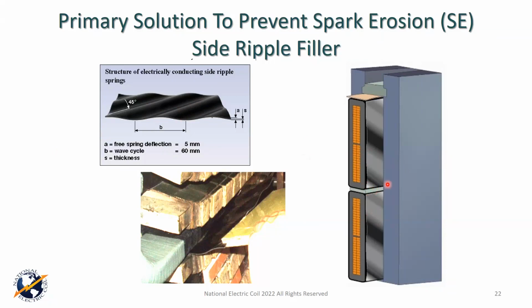Now, one thing, just as a curious note, is you've got to be careful of what's called bird's beaking. And I told you about winders and their creativity. When you cut this material, you've got to be careful of the areas that may go near the coil, because that's a pretty sharp corner right there. Over time, because of the 60 cycle vibration inside the machine and other aspects, it can actually wear a hole in there. Traditionally, you try to orient it so the bird's beaking isn't against the core, or you actually radius this area out so it can't be point loaded to deteriorate the insulation.